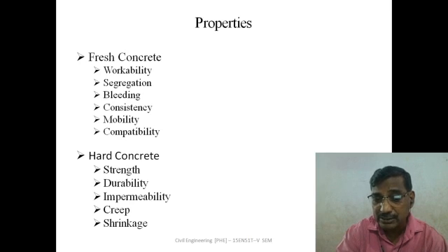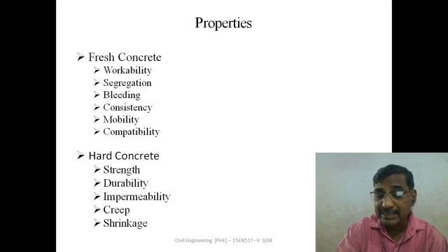Change in the size and shape of the concrete is because of the liberation of stress and strain due to loading for a long period. The stress and strains are induced in the concrete. Because of the induction of the stress and strain, some changes in shape and size of concrete will take place after a long period of loading. That is called creep.